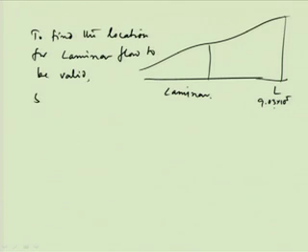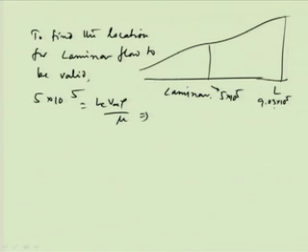we take 5 into 10 to the power 5 as the limit: till that it is laminar, and afterwards turbulent. So, this is equal to L critical into V infinity rho by mu. From there we have seen V infinity rho by mu is equal to something, so we can get L critical is equal to 1.107 meter.